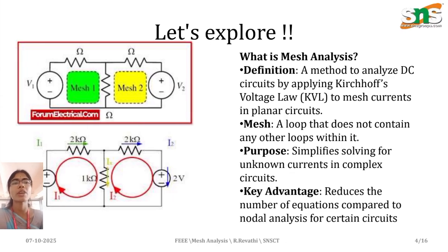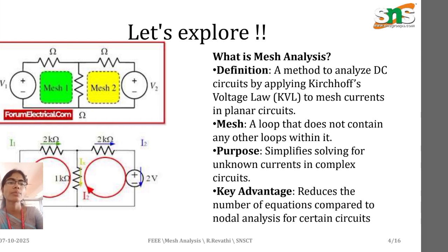It is a method of analyzing DC circuits by applying Kirchhoff's voltage law to mesh currents in planar circuits. A mesh is a loop that does not contain any other loops within it. The purpose is to simplify solving for unknown currents in a complex circuit. If n number of loops are there, there are n mesh currents. It reduces the number of equations compared to nodal analysis for certain circuits. These are the things we are going to solve in mesh analysis.